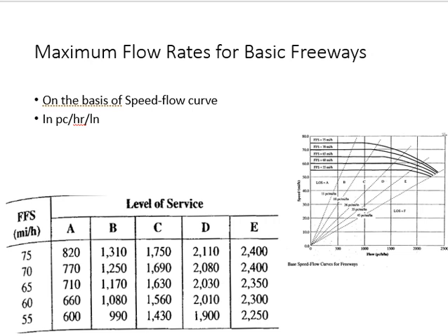Something which I mentioned earlier as well, every level of service has a maximum flow rate. You can see it's a line, right? Level of service A is up to this line. So you can see the line is intersecting the curve at a particular point. At this point I can go to the x-axis and see what is the flow rate. That flow rate is the maximum for A, right? Because after this the line of A is not there. Get my point?